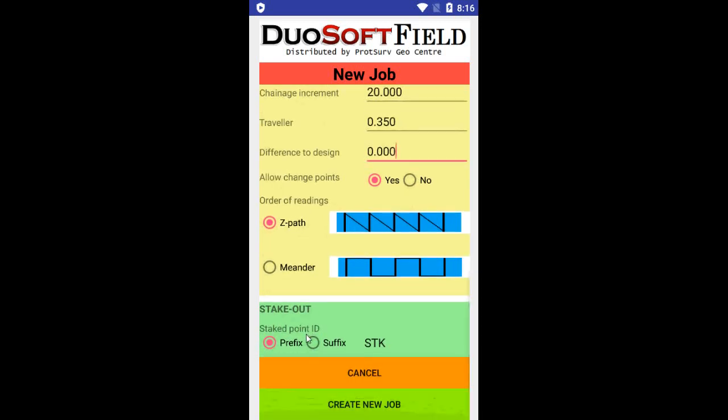The stakeout options, this is the option that is applied when you are saving stake points. When you save that stake point, you have an option to include a string, this string here, STK, in front of or after the name of the point that you're staking out. The prefix means you'll have this string STK before the name of the point, and the suffix means you'll have that string after the name. Okay, so that is a little bit on the setting options that you have for a job.